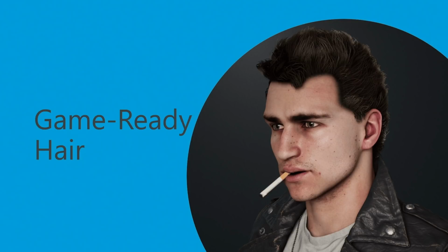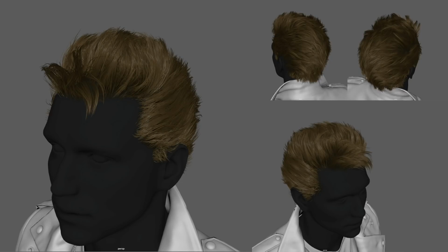And the target platform could change, specs may change, and we didn't want the artist making the hair to have to go through a whole bunch of processes to change it. We wanted to automate this and make it as fluid as possible. So in our case, we're using Maya's interactive groom splines to comb out hairstyles. This is a process that's traditionally used for film and animation. But really for Houdini in this process, any software package that can export splines works just fine. So it's really agnostic on what software you actually want your hair artist to make their hair in. So we just export the IGS data out as an Alembic cache to process in Houdini.